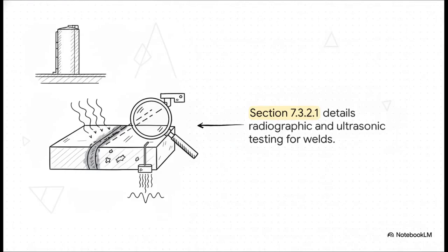To validate the integrity of the towering shell itself, we really have to look beneath the surface. Critical butt welds must undergo complete penetration testing. Inspectors rely heavily on radiographic examinations, which is essentially X-raying the welds, or advanced ultrasonic testing. These methods reveal hidden internal flaws, lack of fusion, or porosity that a simple visual inspection could literally never catch.